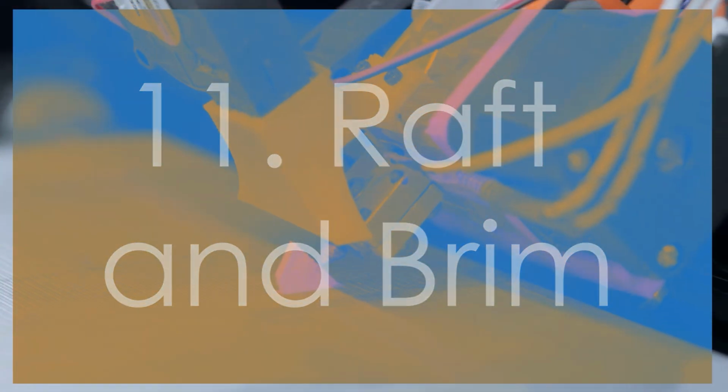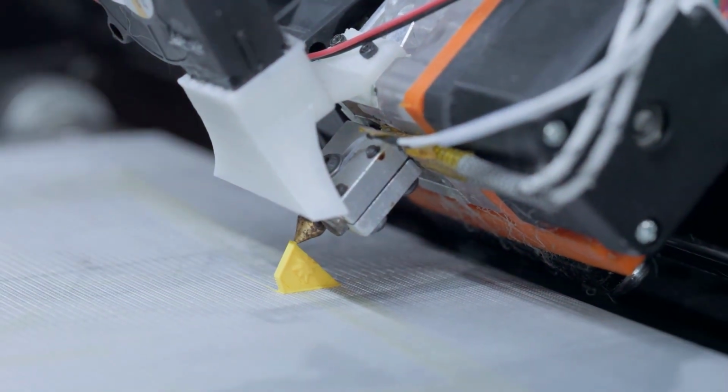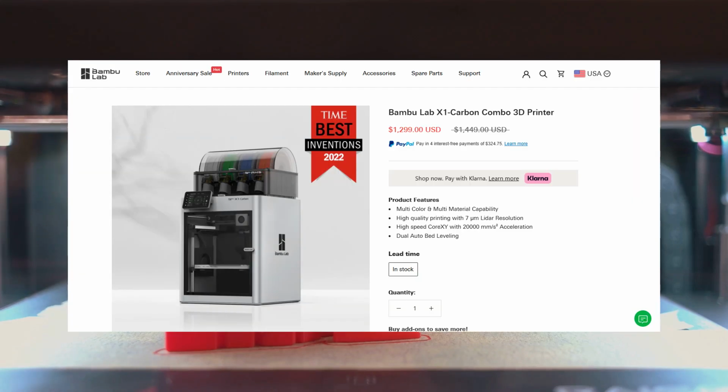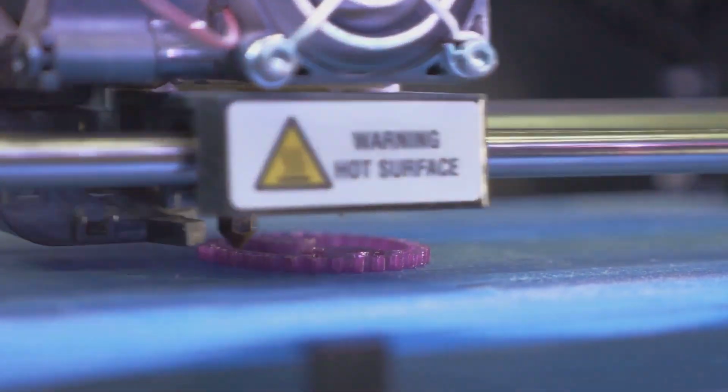Raft and brim are techniques used to improve print adhesion to the bed. A raft is a base layer printed under the object, while a brim is a single layer border around the object. They help prevent warping and improve stability during printing.